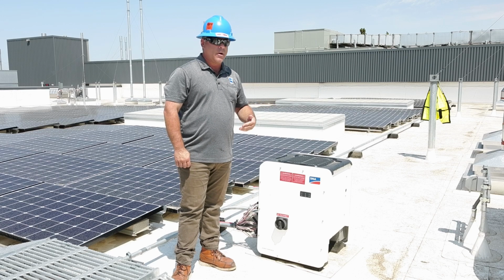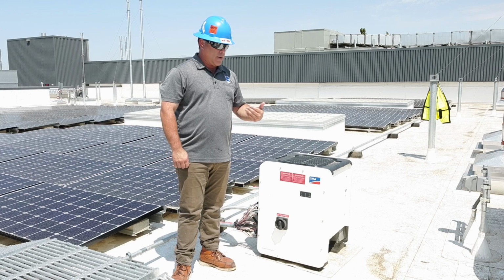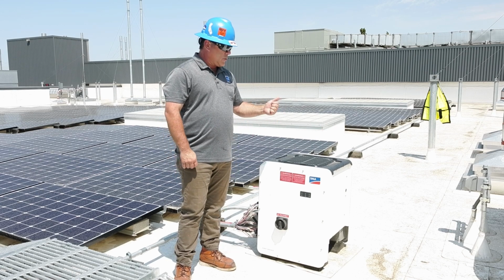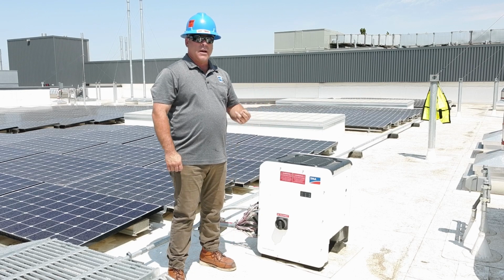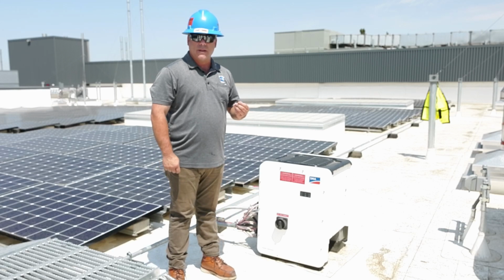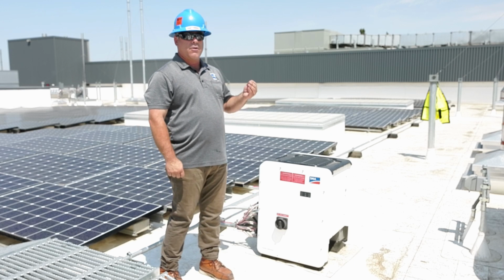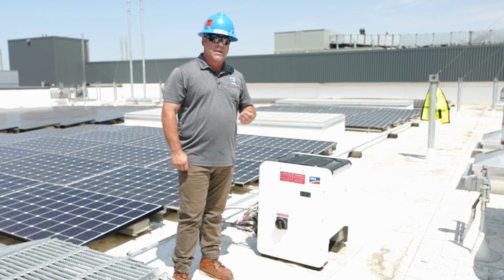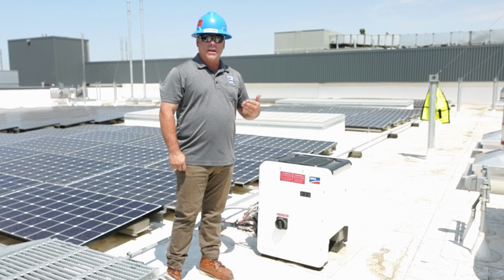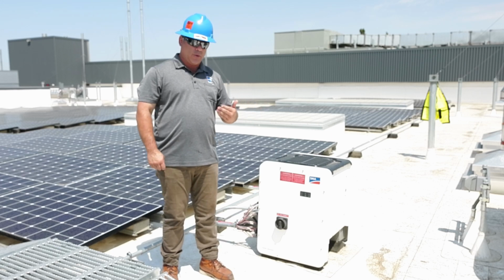We'll go through the parameters. We'll open up the windows, and we can see the events. There's going to be a log of events, when it turned on, when it turned off. It'll also tell us how much it's producing, voltage, amperage, how the DC is doing, how many of the strings are working. If we have 10 strings, it'll give us a detail of all 10 strings. If there's 12, it's going to be 12. If one of them is not producing, that's the point that we can start looking into a little bit of troubleshooting. Why it's not producing?